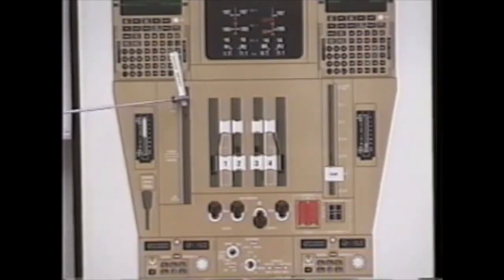Speed brakes. Speed brake lever in flight cannot go beyond the flight detent. It's physically impossible to bring it beyond that point. There is a lever lock there that prevents that operation from occurring. On the ground, the lever lock is removed so the speed brake handle can be pulled all the way to the up position. Unlike the classic 747, you can use speed brakes in flight with flaps extended on the 400, not recommended beyond a trailing edge flap setting of 10.